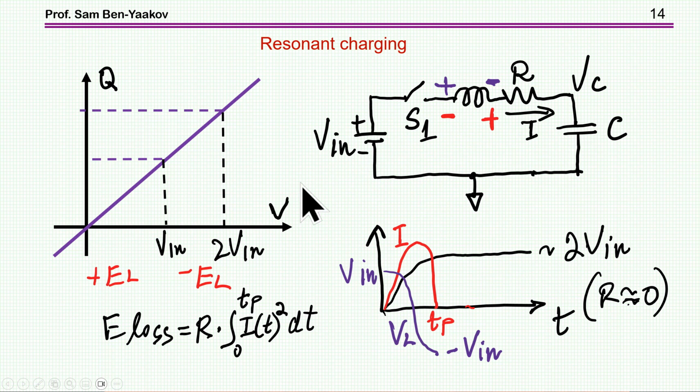Now, if I look at this chart here, what I understand is that I have a process that goes up to here. This is the energy stored in the capacitor at this point. This now is not dissipated. It is stored, okay? Stored in the inductor. So now this energy, plus the energy from the source, is continuing here the charging up to this point.